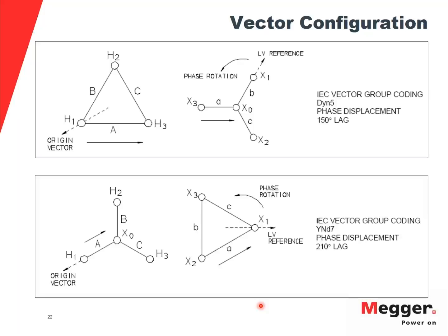All it means is that you need to use an appropriate amount of voltage to get good readings. So if you ever run into those kinds of cases, you may want to use a three-phase source, as I said, or apply the voltage phase to phase, or try to energize from the secondary winding, or if you have a source that can apply 1000 volts and your winding can take 1000 volts, you may want to try those kinds of things.